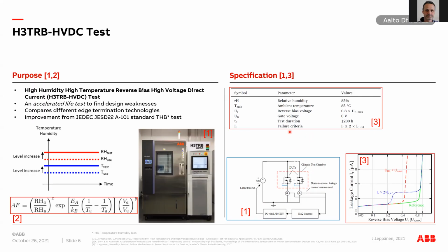So again, referring back to how we test these limits, we have the operational limits when something starts electrically failing, so that the circuitry is not functioning anymore as it should, but there's no permanent damage yet. Or then we exceed the destruction limits, like we see here, so that after a certain failure mechanism has propagated far enough, the smoke comes out and it's not working anymore.